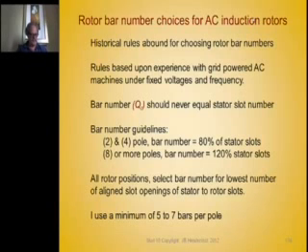And they're particularly stringent and difficult for single-phase motors because some combinations are just terrible and the motor won't even start with certain bar combinations. But that whole topic tends to be mitigated and go away if you could control frequency and voltage separately. So it's not so important.